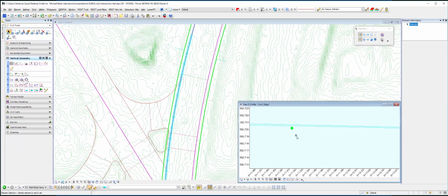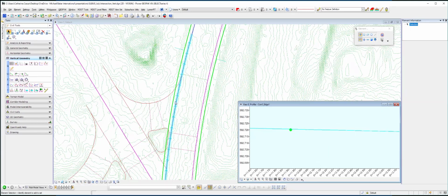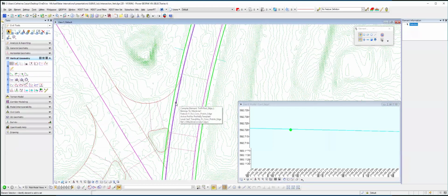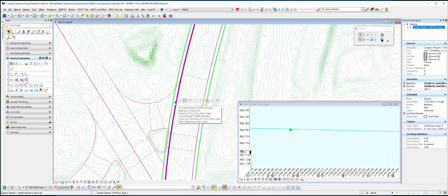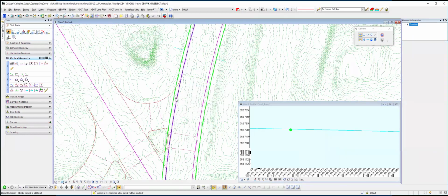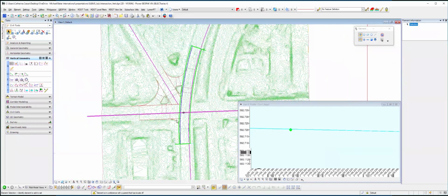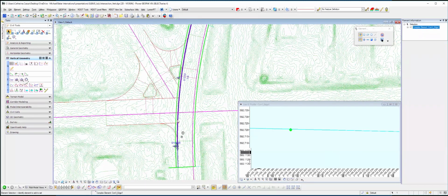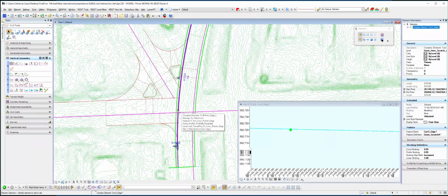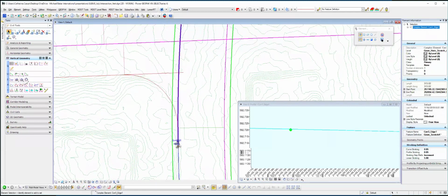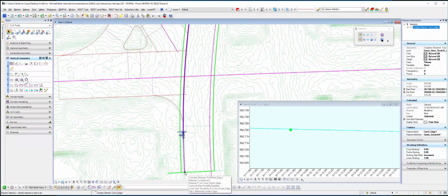So it's just a little issue, especially in this SS4 version of the software, where chording comes into play. What's happening essentially is each model has a chorded component to it. You have a template drop, so this was done with a specific template drop and a particular linear stroking, and then the profile curve stroking. And that will dictate the number of points along this line. When I did the offset line, it essentially inherited the linear stroking. However, it starts at a different point. So 0, the origin of that stroking, becomes this point right here where it began, not necessarily the same stroking distance or location as this.